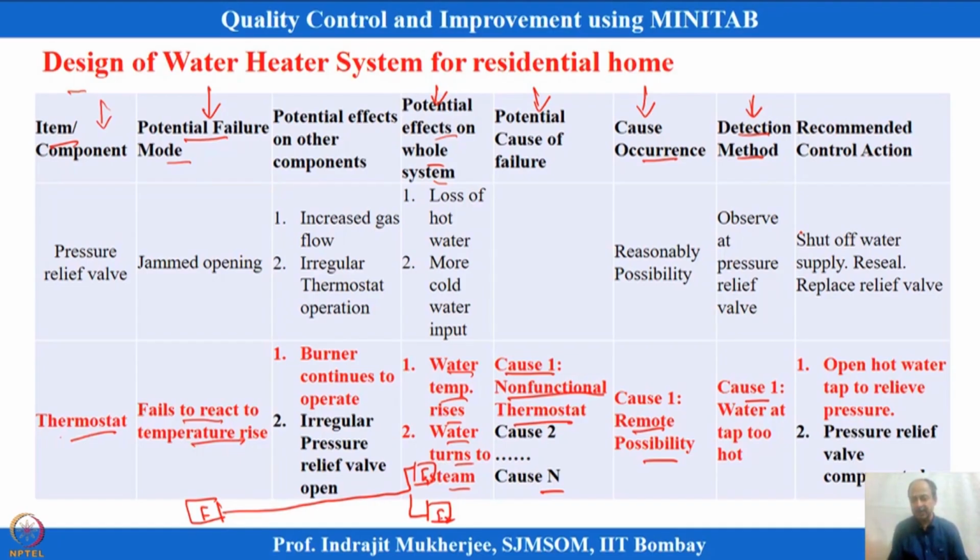Okay. And then the recommended action in case it fails. What is the recommended design control that we have already mentioned, already in place in the design? These are the recommended control actions in case it fails because of this cause, and what action is to be taken. What is important is the failure mode and the severity of the effect, how severe it is. That is also important, and then what the causes are, because if it is very severe we have to take action, we have to block those causes which are creating this failure mode basically. Okay. Then for every cause we also need to identify the frequency. Then we can think of whether there is any detection method to identify if there is a failure because of this cause, and accordingly we have a recommendation for that.